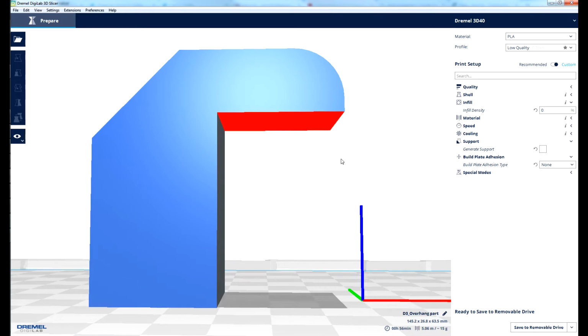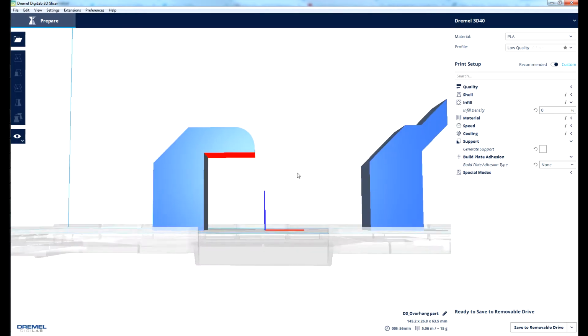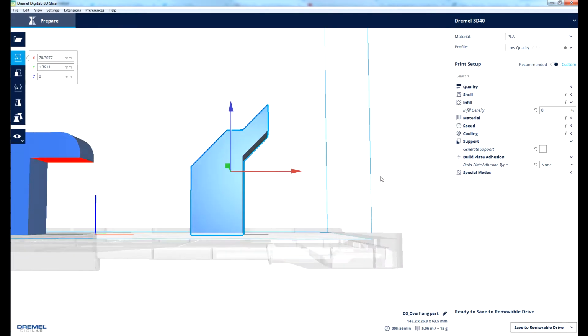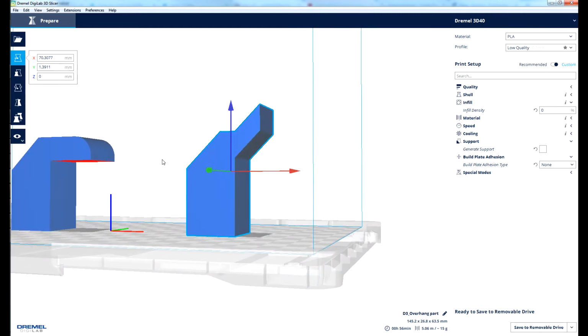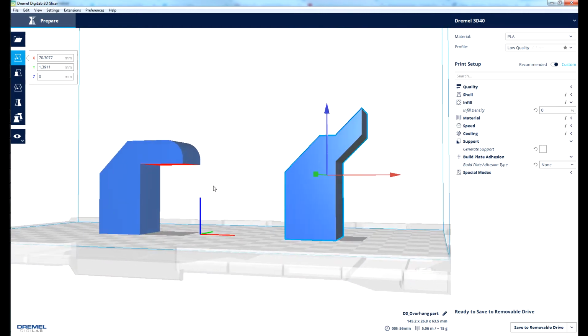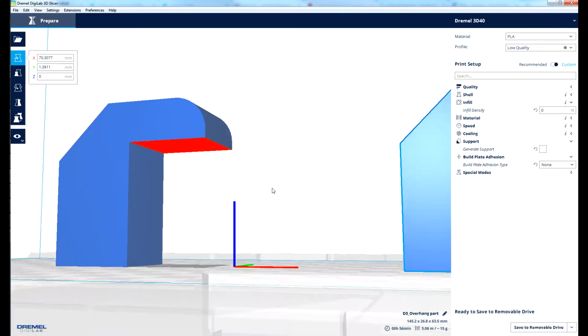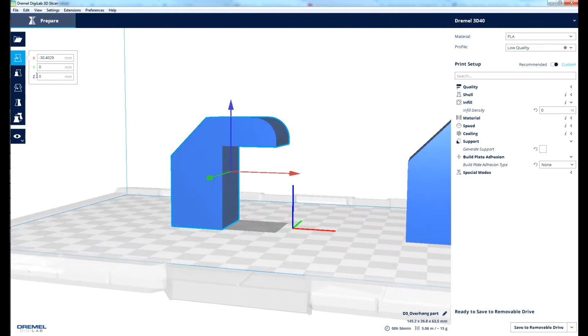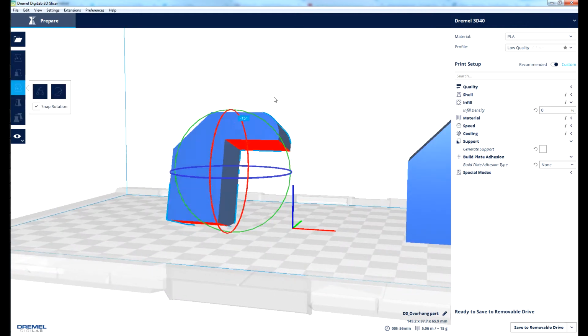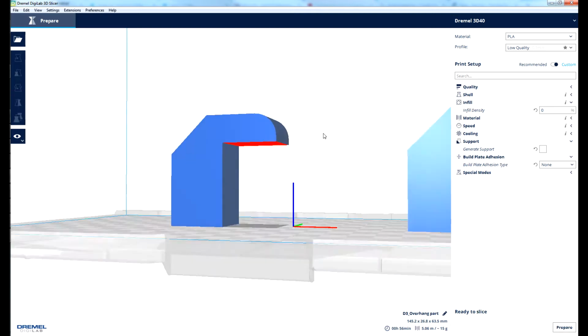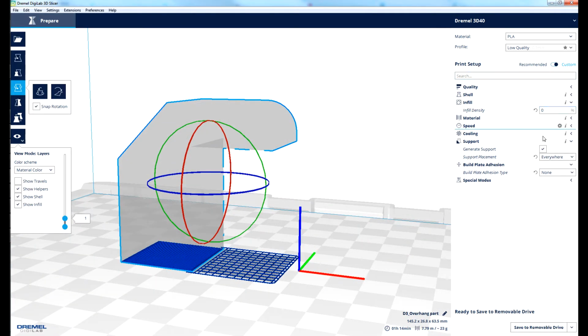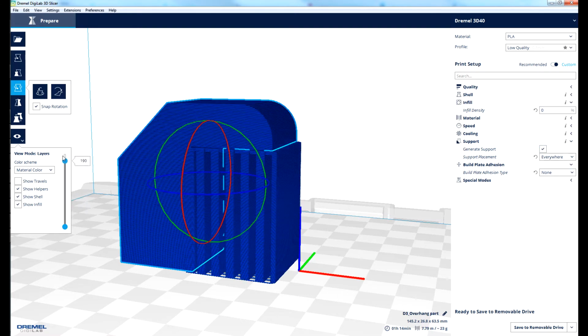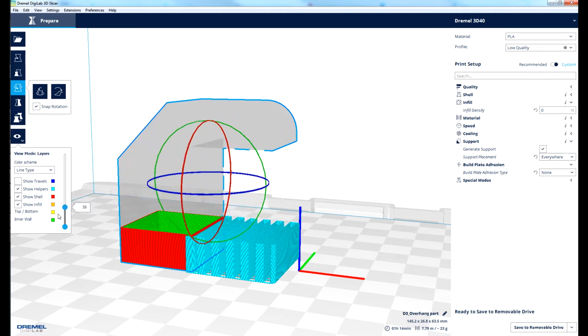Of course, there are exceptions, and this is referred to as a part's overhang. A modest amount of overhang can be printed without support, and this is usually limited to about 45 degrees. Slower printing is better for parts with lots of overhang. Features that exhibit overhang are usually marked in red by the slicer. Adjusting a part's orientation can help minimize the need for support structures, but sometimes supports are inevitable. Support structure is a sparse density filler that breaks off easily from your model. We'll talk more about overhang and supports in a bit, and some advanced features.